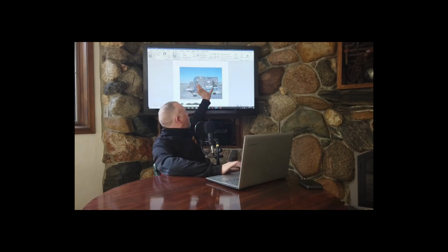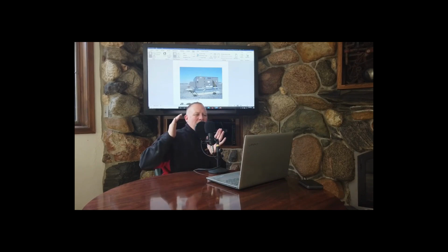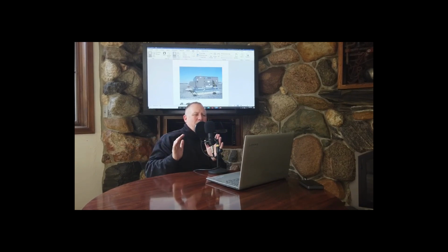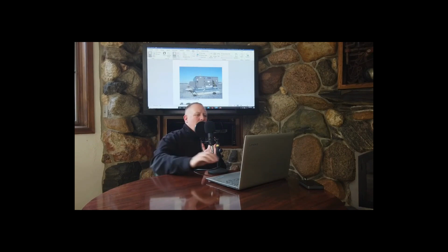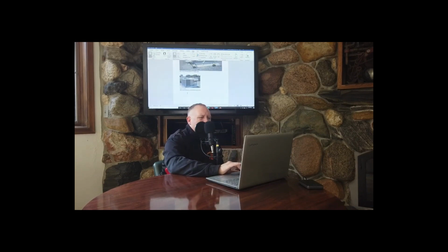Here. The bigger rooftop units can have variable frequency drives on them, on the supply fans. You can pair them with variable air volume boxes, VAV boxes. So once you get into bigger and bigger capacities for those rooftop units, we can get more features on it and therefore get more zones of control. And like I said, they go up to 150 tons. A few manufacturers make some that are even larger than that. But once you start getting really, really large, you'll probably want to go the chiller route.